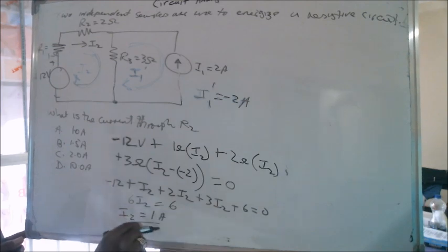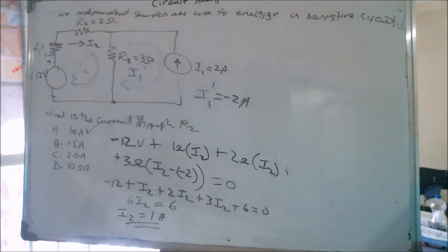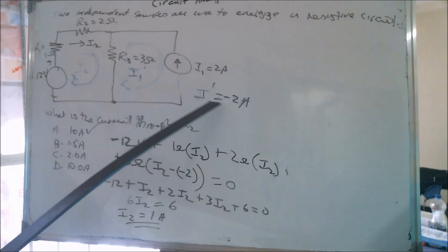See that clearly? There's no need for you to analyze the second loop. Taking KVL around this loop, the voltage source and all these resistors times the current, with the value of I1 already given, except that we have to know it's opposing the flow of our clockwise motion.